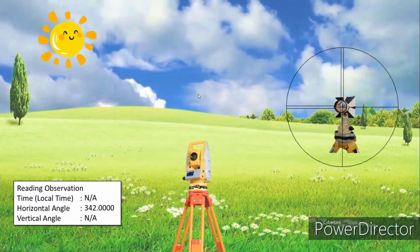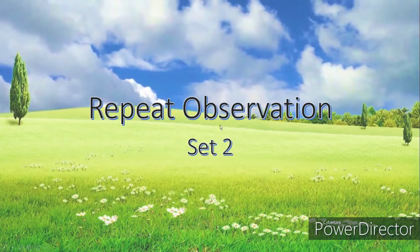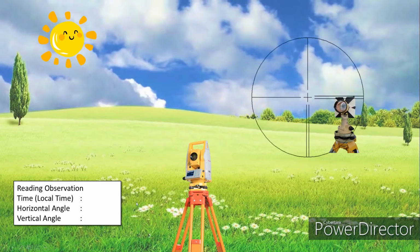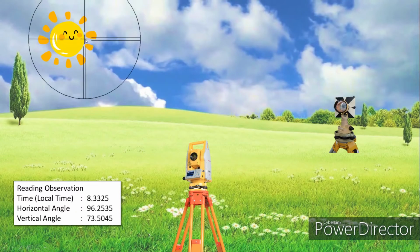Next, we continue and repeat the observation for set 2. The procedure is totally the same as the procedure for set 1. We read the observation on the back side and jot down the reading, then move the crosshair of the total station to the right hand side of the sun.